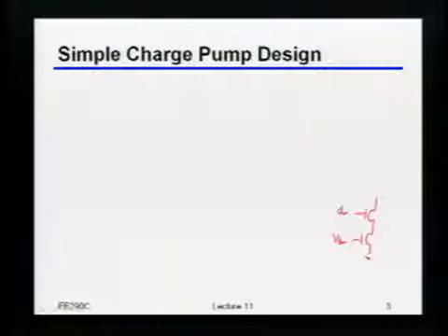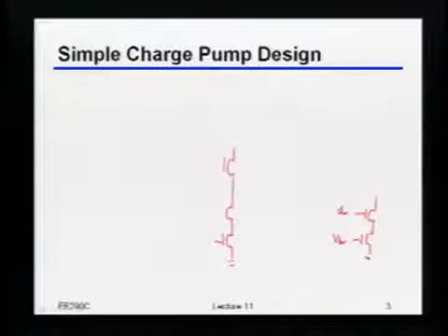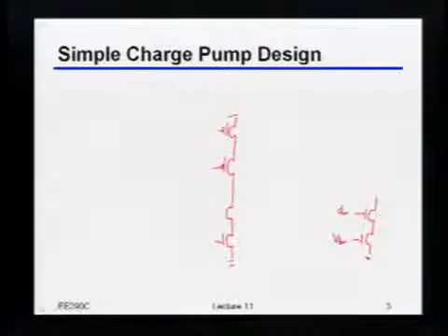We drew one version of the charge pump, which I'll sketch on the side over here, where we had some current source device, and then some switch that was either connected to down or up, depending upon which direction you were going. I want to quickly redraw a slightly different version that turns out to be more common in most of the implementations I've seen. I won't draw the full thing, I'll really just draw the output stage, but recall that you have to match everything up correctly.